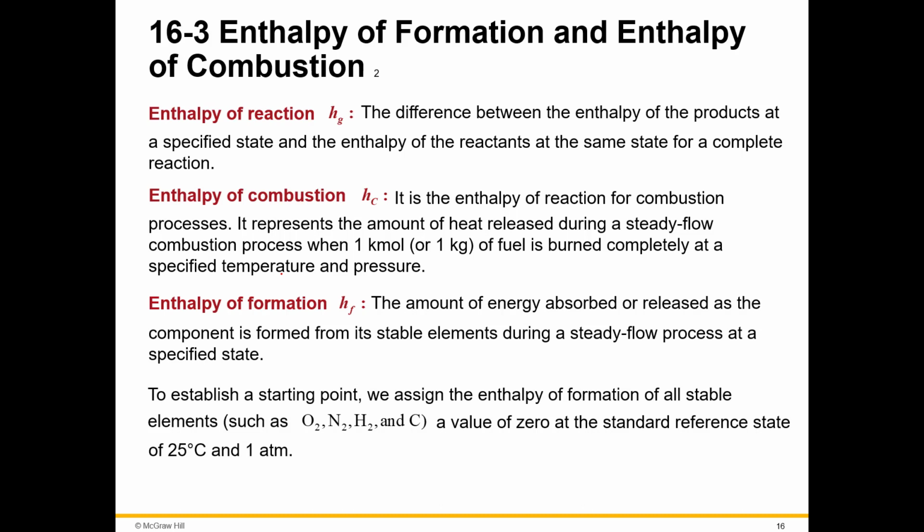So that's where we get our starting point. And then we can start looking at those states and at a steady flow process, trying to find that enthalpy of formation, and then comparing those two states for the reactants versus the products to get the enthalpy of reaction. And then looking at what is released during that steady flow combustion process when 1 kilomole or 1 kilogram of fuel is burned completely at a specified temperature and pressure.